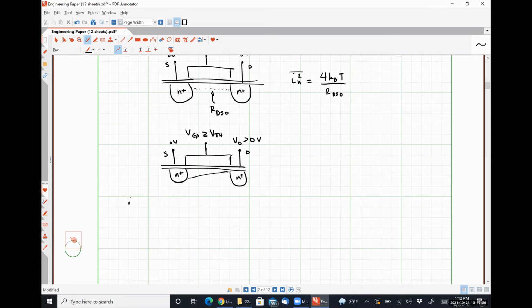So our drain current noise spectral density is going to be 4 kBT times (mu n C ox W over L) quantity squared, multiplied by 1 over our bias drain current ID, times the integral from 0 to VDS of (VGS minus the voltage at whatever position we are at physically across the channel minus VTH) quantity squared dV.